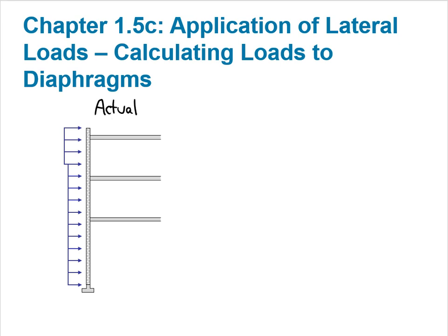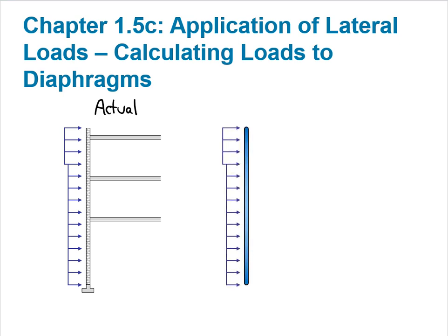If we idealize the wall as a vertical member, the best idealization is a pin support at the foundation because the wall doesn't move vertically or horizontally here. At each floor diaphragm, the floor will move horizontally some, so the most accurate idealization is springs at each diaphragm level. We can analyze that, but it is a complex and time-consuming process.